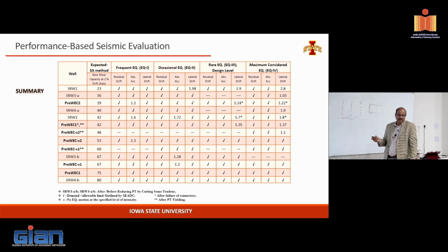So I've shown you the single rocking wall, the amount of steel we put in. I've shown you how this is connected. Just run a strand or two, that's your connection. And they're doing really well, because most of the energy dissipation is actually coming from the impact itself. Each time it rocks back and forth, it's not a significant amount. You just take 3% energy out. Next impact, it takes another 3% out.